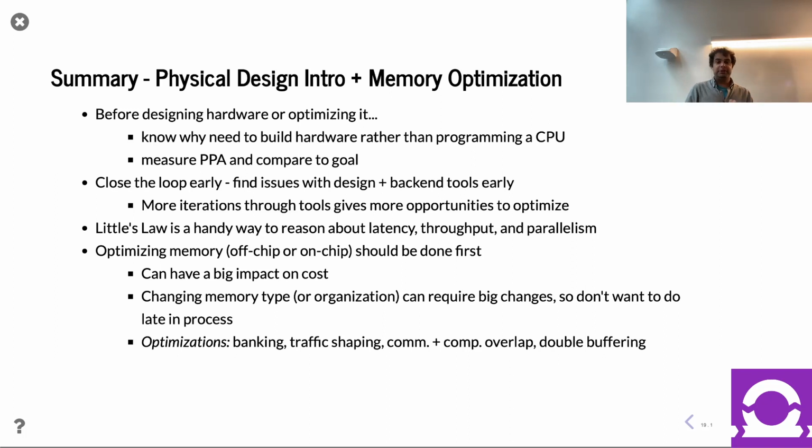As always, see the big picture and close the loop; find the advantages of closing the loop early. By that I mean not just getting something functionally working in Chisel early, but actually passing that Chisel through the tools, getting Verilog, and then passing that Verilog to your backend tools early. You can see issues early on. The last thing you want is to spend a year writing Chisel, convince yourself the design is perfect, no bugs, perfectly verified, and then pass it on to your hardware design team, and they take the Verilog and say, this won't work. And now what? No surprises. Get the Chisel working as early as you can, and get the Chisel to Verilog to the CAD tools as early as you can.